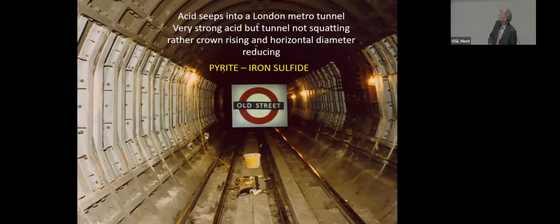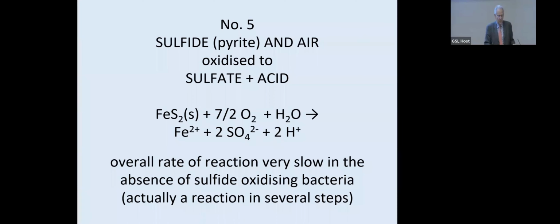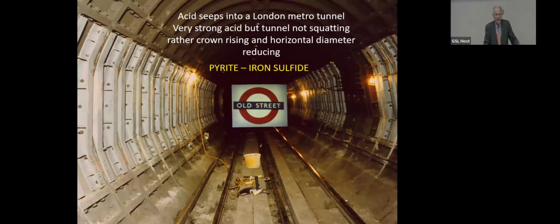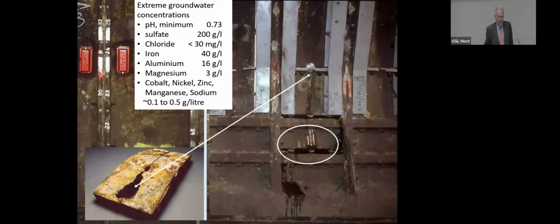So, that's basically it. The lining all cracked, and that's it strapped up prior to it being replaced. It was over-tunneled. What seemed to have caused the cracking was they were monitoring the stresses in the lining because they knew the tunnel was squeezing in at knee height and being pushed upwards.